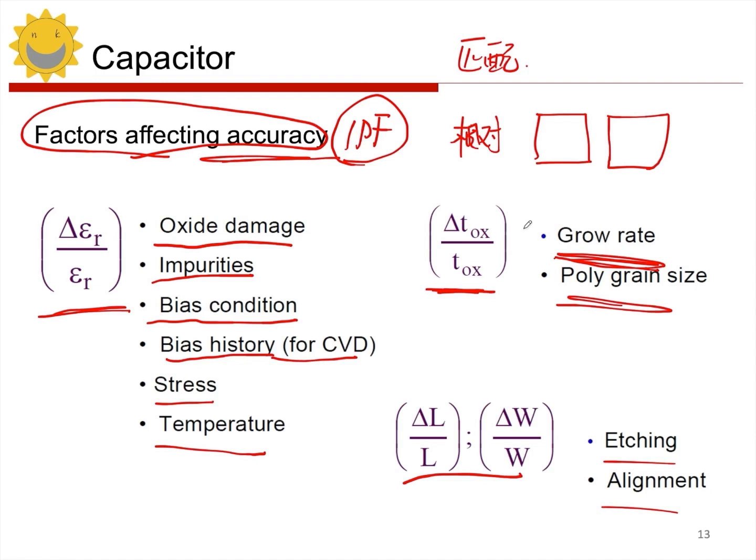It is precisely because it has this relative matching degree that this capacitor can be used for some signal processing, such as the switched capacitor circuits we commonly use. Switched capacitor circuits are the most commonly used circuit structure in current mixed signal circuits. They use switches, capacitors, and amplifiers to form circuit structures that realize analog signal amplification, integration, addition and subtraction operations, etc., right? In this process, capacitors are used for charge transfer and signal operations. We'll use the ratio of capacitors like C1 over C2 for precise calculations. This concerns capacitor accuracy.